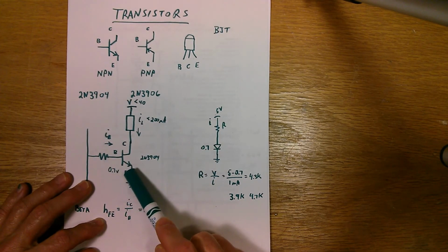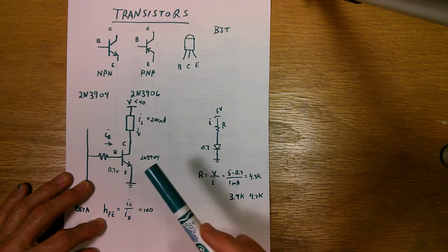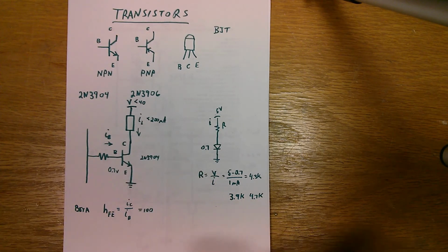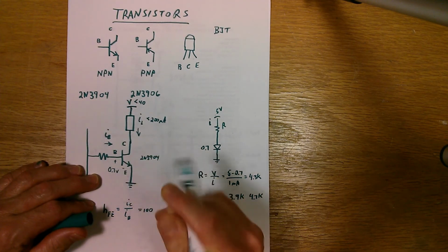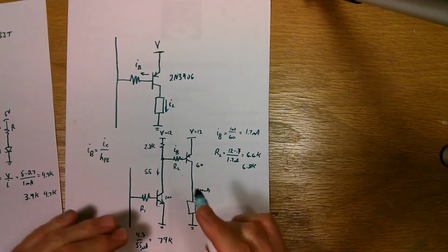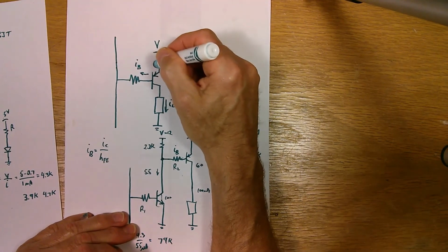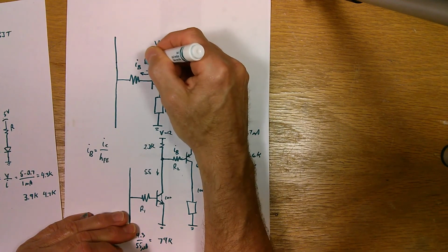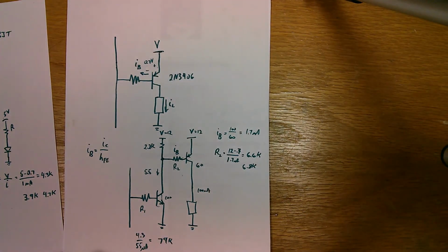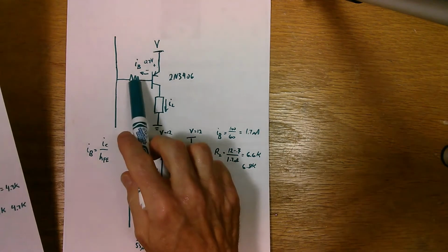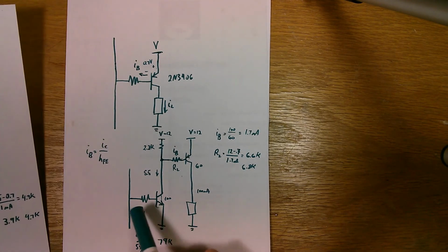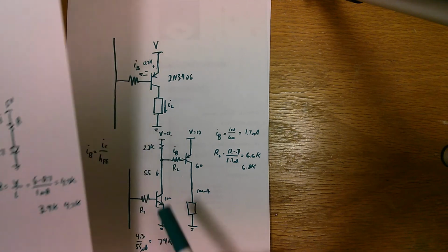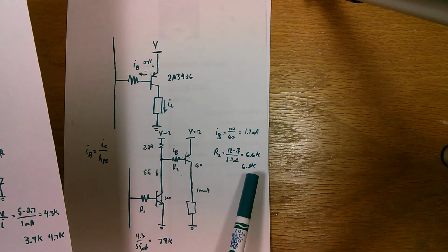Remember that both transistors will have a voltage drop across the base emitter junction. In an NPN, the polarity is of course this way, plus on the base and minus on the emitter. If I go over to the PNP, it's the other way around, it's plus on the emitter and minus on the base, but it's still the same voltage. You've got to take that into account when you're calculating your base current limiting resistors, if it's for microcontroller voltages. With 12 volts, you can almost ignore it. It doesn't make that much difference, especially when we're picking our preferred values.